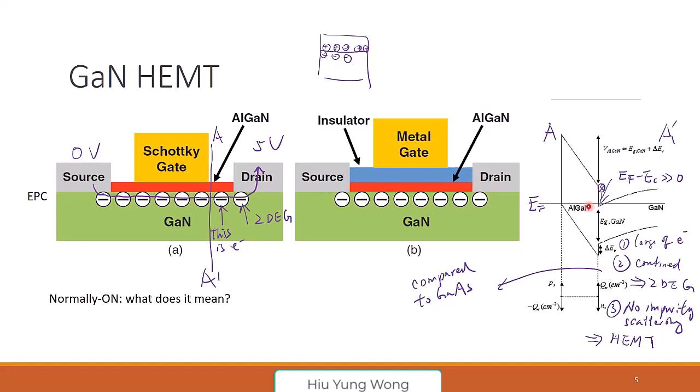Now, you also ask why, what's the difference, right? Here you see I have gallium nitride, aluminum gallium nitride barrier. Here I add an insulator. This is not an insulator, this is just a wide bandgap semiconductor. Here I may add oxide, aluminum oxide, whatever. This is another style of doing this device, and this can have a few effects, for example, change the threshold voltage or reduce the gate leakage current. So this is just another type of HEMT.